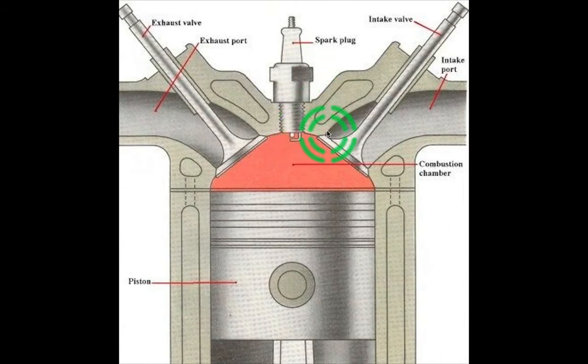The spark, we have nothing to do with the spark thing, but that's where it sits. You see the tip right here. This is why you see this kind of combustion chamber, so strange. I remember on my 3S GTE engine, once upon a time, you have two sizes of spark plugs. For the Nissan petrol engines, your spark plug is way up till here. And actually by mistake I installed the wrong spark plug, which went all the way till here, but nothing happened. Imagine if my combustion chamber looked different.